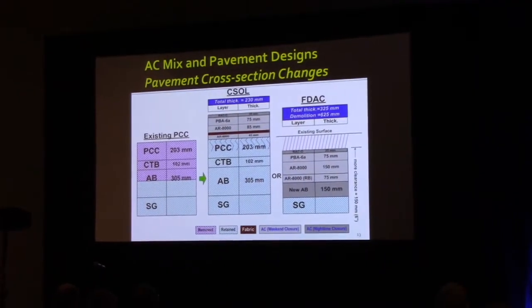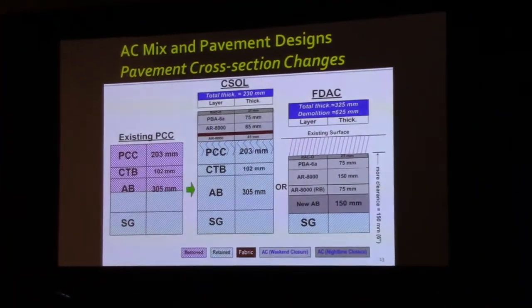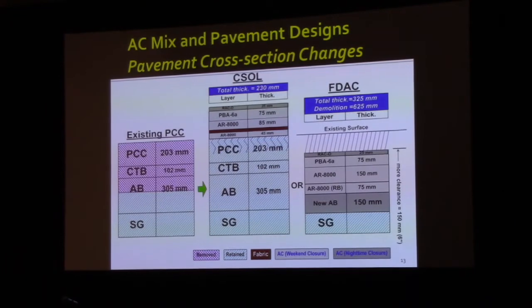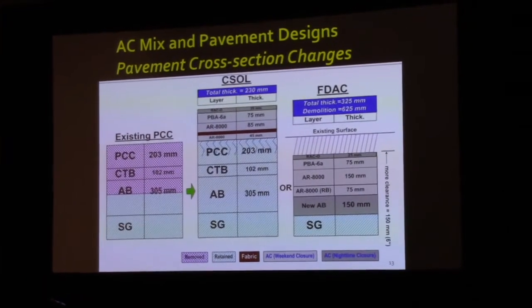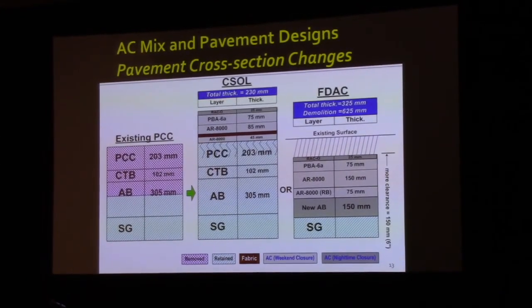This is what the two different structural design sections were employed in this project. You can see what the original existing pavement looked like. You have a crack seat and overlay, and that's pretty much the bulk of the paving that was done. That full depth asphalt was for the sections under the overcrossings, because what they wanted to do is pull all that material off so they can drop the section of pavement down to increase their bridge clearances.